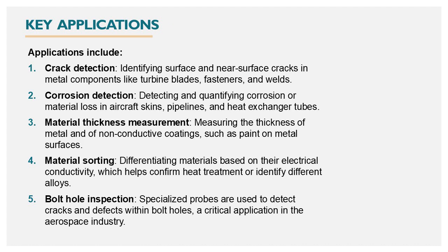Eddy current testing key applications. ET is a versatile inspection technique used across many industries. Applications include, number 1 is crack detection, identifying surface and near-surface cracks in metal components like turbine blades, fasteners, and welds. Number 2 is corrosion detection, detecting and quantifying corrosion or material loss in aircraft skins, pipelines, and heat exchanger tubes.